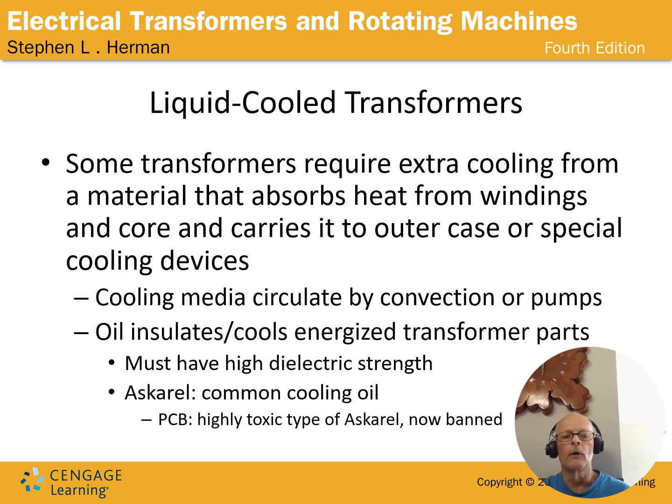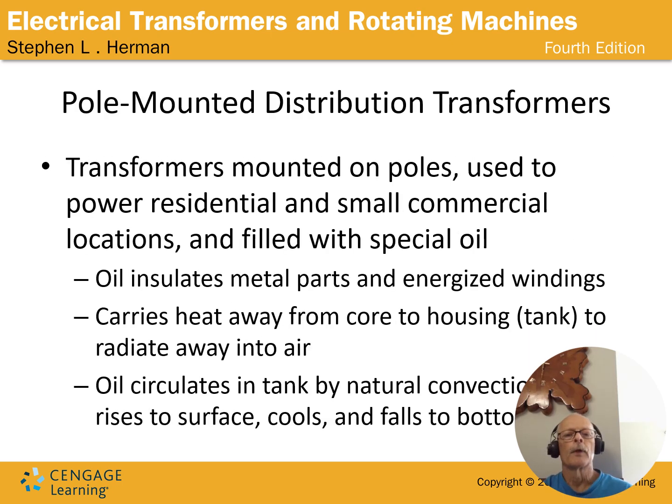And so this Ascarel that I'm talking about is the polychlorinated biphenyl, PCB-containing oil that we've got to be careful with. If you see Ascarel, it'll throw up a red flag to you instantly. Okay, pole mounted distribution